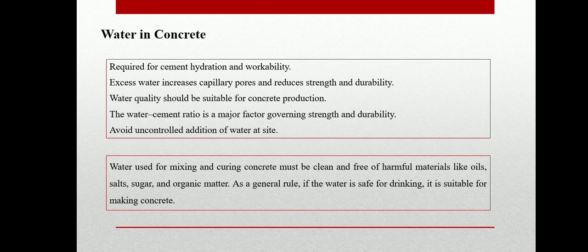Water quality also matters. As a simple rule of thumb, if the water is safe enough to drink, it is generally suitable for making concrete. It should be free of oils, salts, sugar, and organic matter. And a word of caution for site practice: avoid the uncontrolled ad hoc addition of water at the site just to make the mix easier to work with. That is one of the most common and most damaging practices that compromises concrete quality in the field.